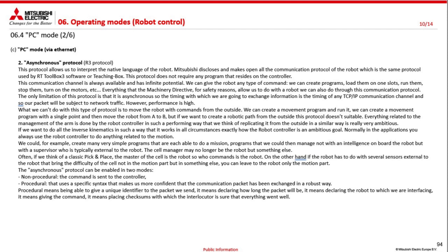What we cannot do with this type of protocol is move the robot with commands from the outside. We can create a movement program and have it run. We can create a motion program with a single point to then move the robot from A to B. But if we want to control the robot's motion from the outside, this protocol does not allow it.